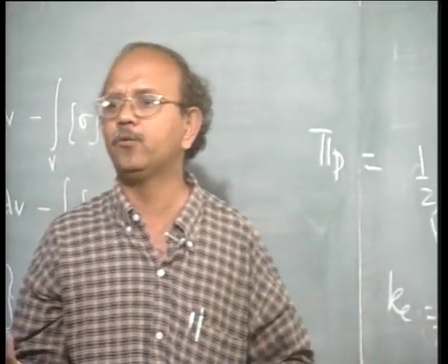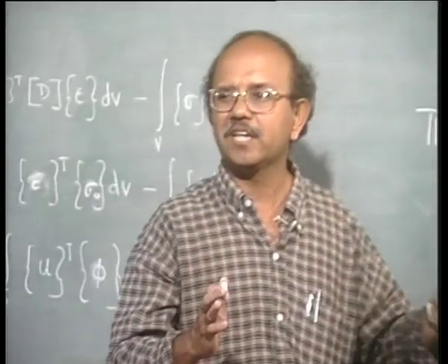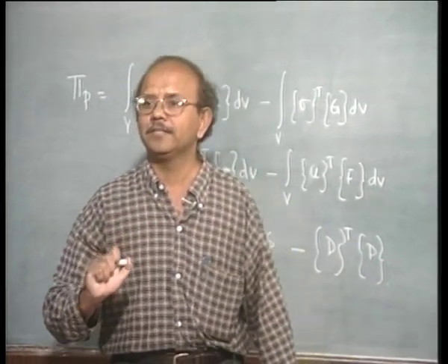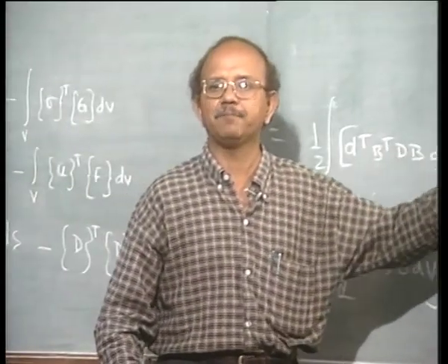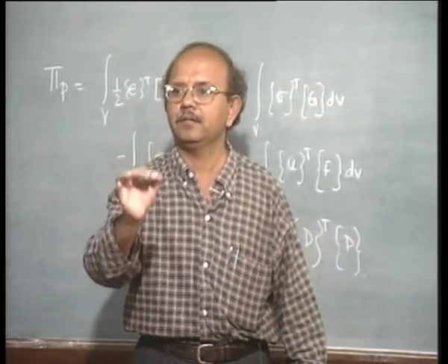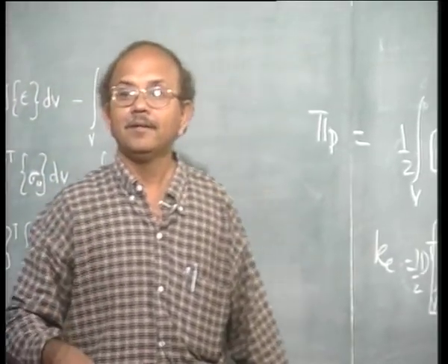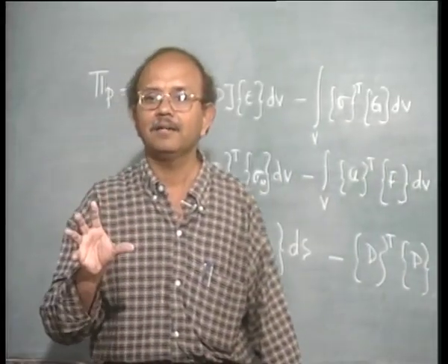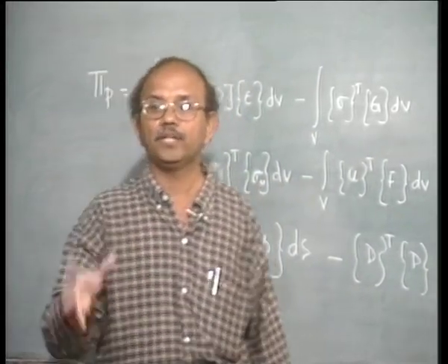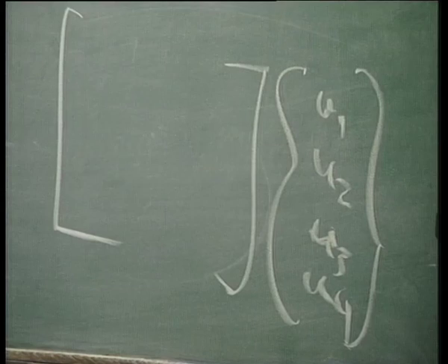Zeros, that is it. That is what I have been looking for. It took you quite a while to find out. So k1, minus k1, 0, 0, minus k1, 0, 0 and so on. What is the advantage now? If I write the second element also in the same sense, the first row is 0 0 0 0, then the second row becomes 0, k2, minus k2, 0 and so on. Then they can be straight away added. They are matrices of the same size, and the u's sitting there are the same u's. So u can be taken out and I can add them.